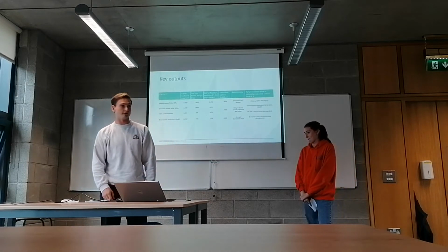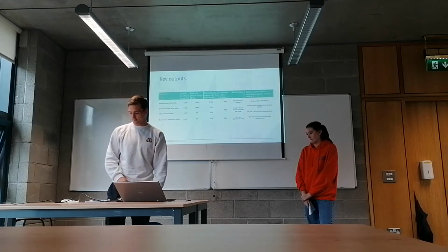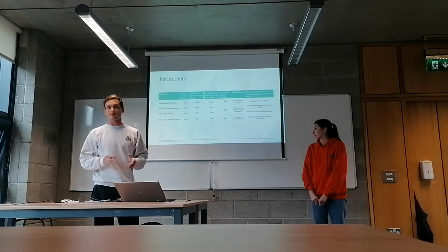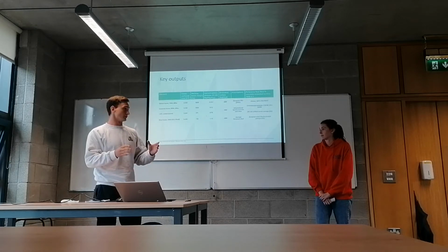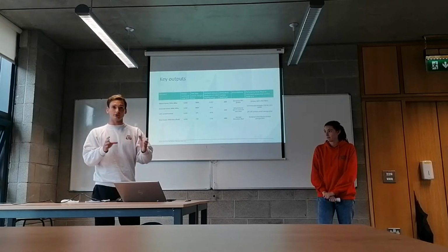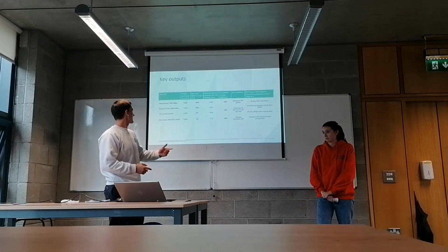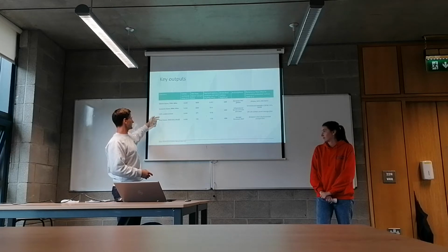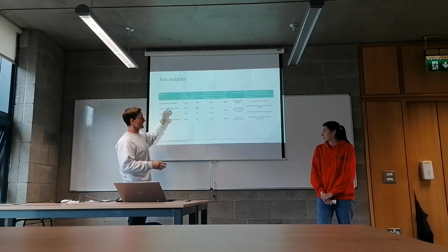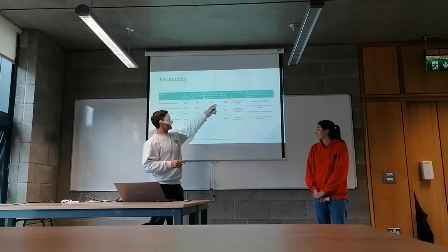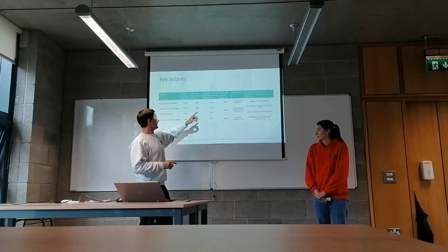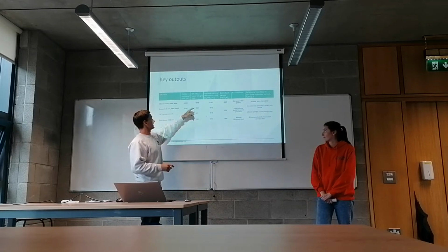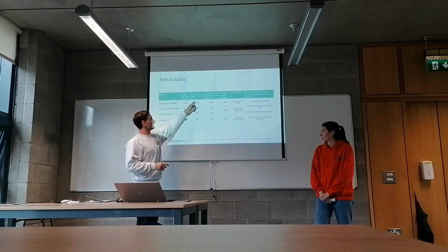Right, so to summarize what was actually in the article, the key output is there is no perfect material. You have to decide which material to use in which situation. To emphasize this, they had a table where they have different materials like wood, concrete, steel beams, and they have the same length, they have the same amount of embodied carbon, and they can hold up the same strength, but they differ in cross-sectional area and weight.